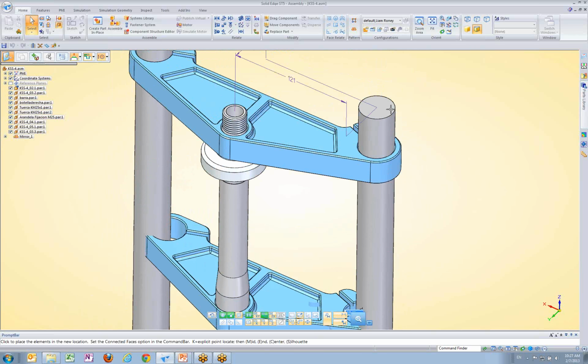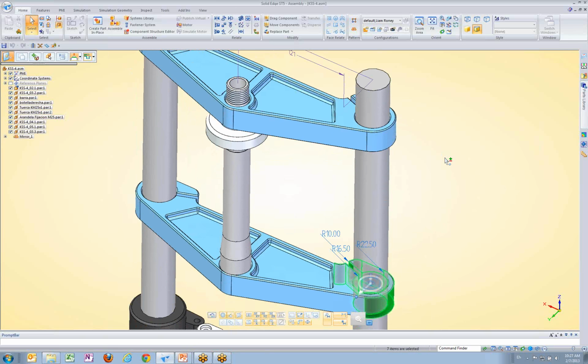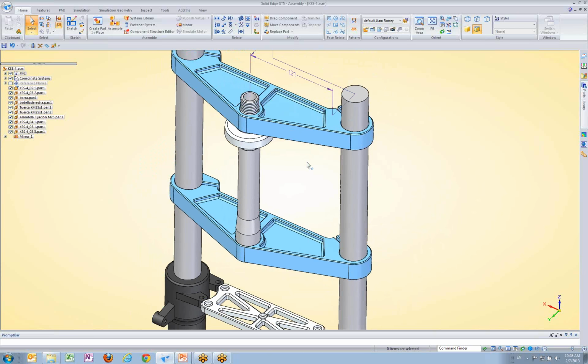And I'll zoom up and do what I did before. Just click, snap onto the end of that and click it once. So that saves us a bunch of clicks because we can access those synchronous faces right from the assembly. And I'll hit escape to end that command. We can do a translational planar move to accommodate both those changes we made. That's a nice fast way of doing things.